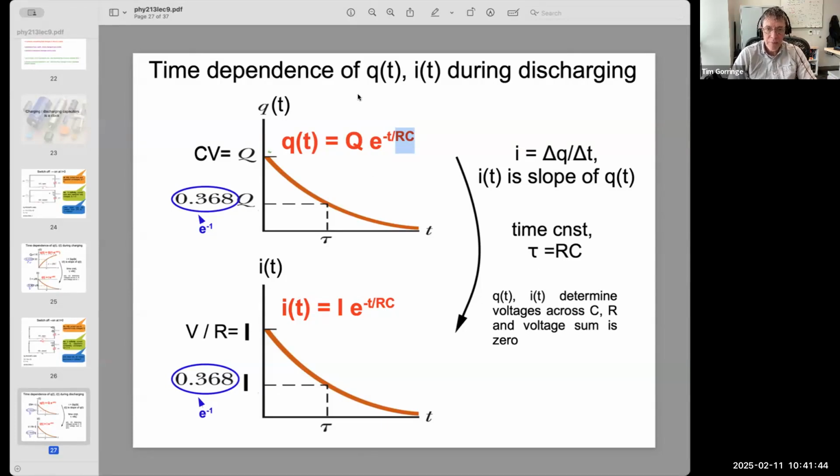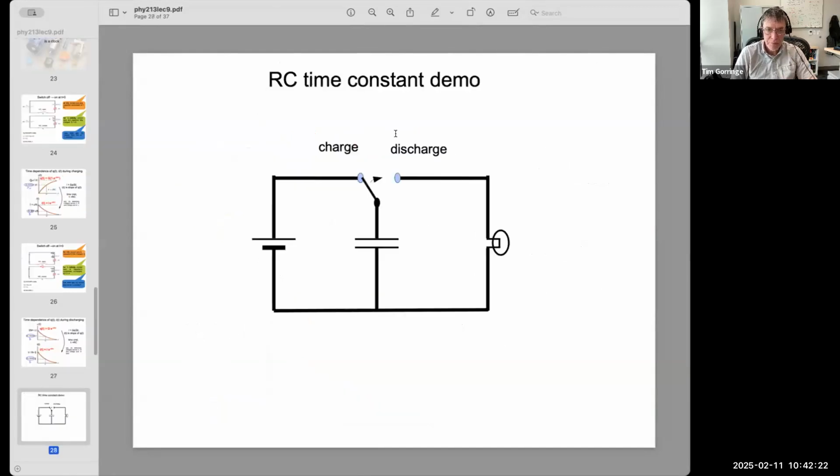And so this is our understanding of discharging of a capacitor. The important point here is that the discharging is not instantaneous, and the current flow between the plates is not instantaneous. It follows an equation that has an exponential time dependence. The exponent of the exponential is a negative exponent, and in the exponent is a time constant that we call tau, which sets the scale of the clock tick or the discharging of the capacitor through the resistor.